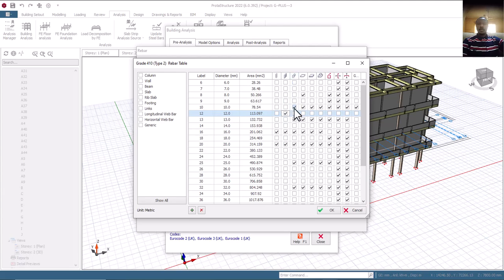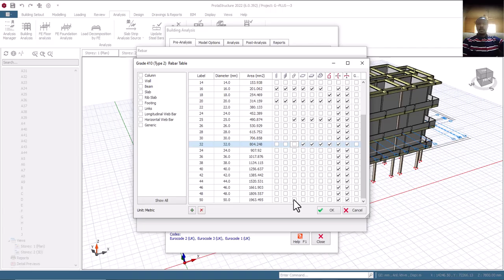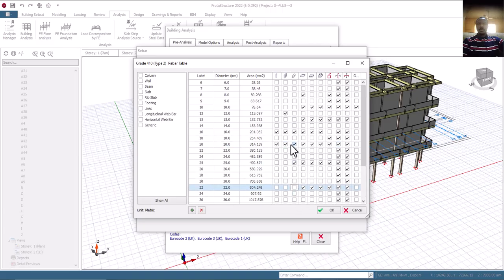So coming to my beam now. For my beam, I'm using 16 and 20, and also let me put 25 there, and then that's all. Is that okay? Just to keep, definitely I will not use it, but I just keep it there. So the moment it's requested for 25, automatically I might need to increase the section of that beam. Because I don't want to use 25, it's too expensive. So I'll come to my slab, come here now, I'm using 12 mm, then the rest I remove. That's for slab. This is slab. Can you see I don't have a rib or waffle slab?